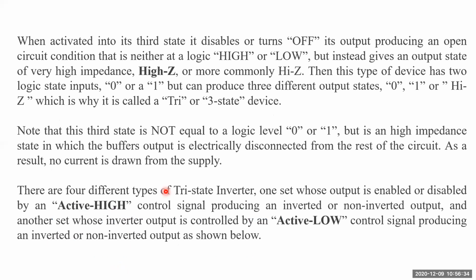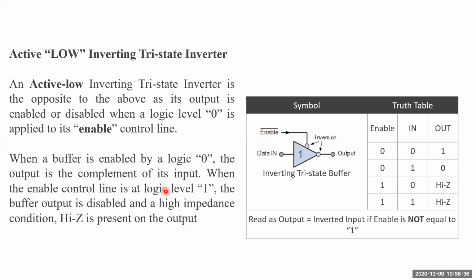But when you come to this active low state, what is happening here? Because a bubble is connected at the switch, if I supply 0 over here, because of this bubble the output will be 1, and that enable will make your switch close. So whenever enable equal to 0, what you read is correct only.